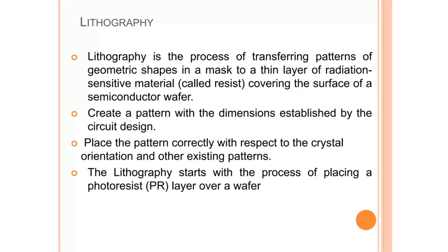So in this video we are going to discuss the lithography process, or sometimes referred to as photolithography. The basic idea of lithography is that you can transfer the patterns of geometric shapes in a mask onto the thin layer, onto the surface of the semiconductor wafer.